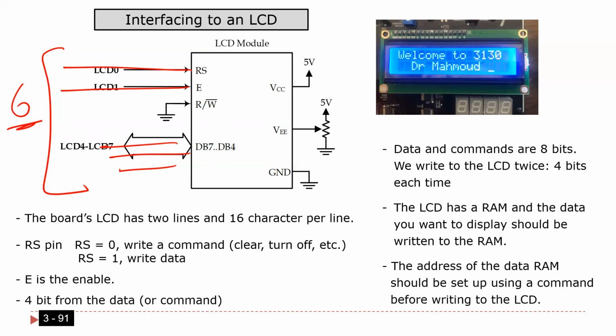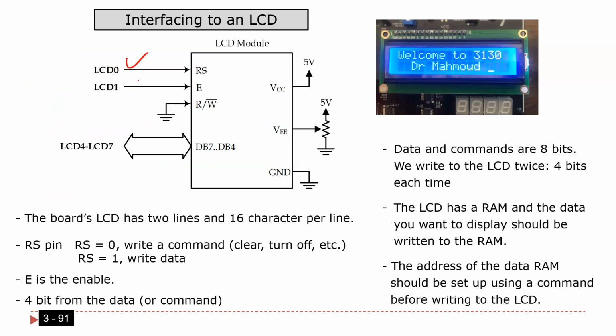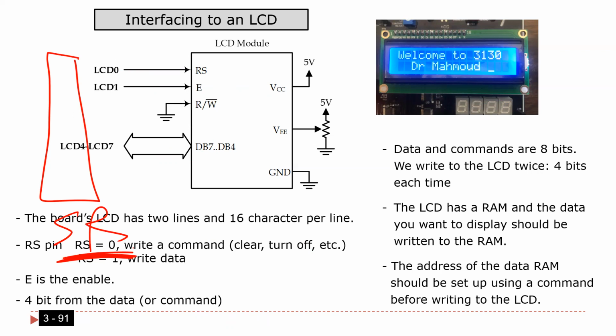So what they did in this design in order to reduce them is, look here, guys. I'm not going to connect these pins directly to the microcontroller, because if I do, I need 6 pins. So what I did, I connected them to what we call a shift register. I'm going to give you more details, just wait. This shift register should be 8 bits. This one has 1 pin, and then I can take 4 here. So 4 and 2, 6, and there are 2 I'm not going to use.